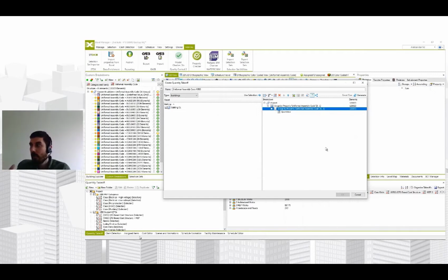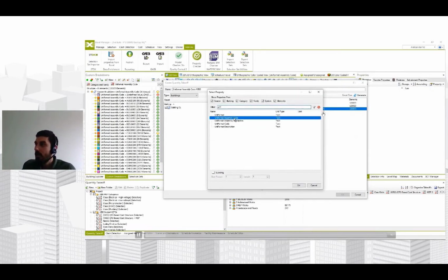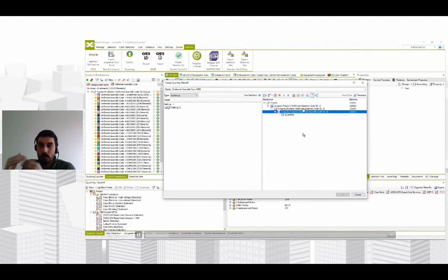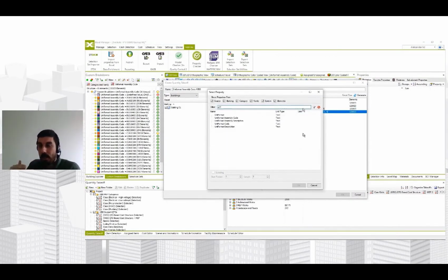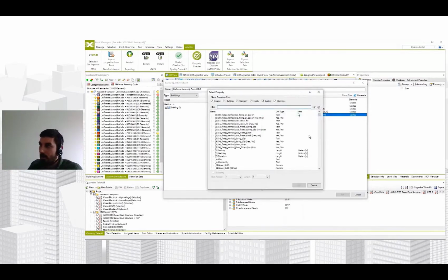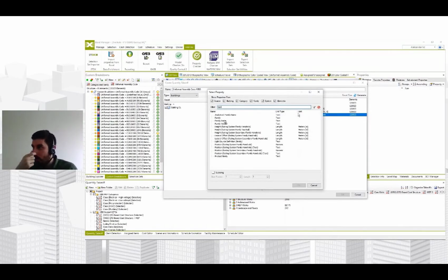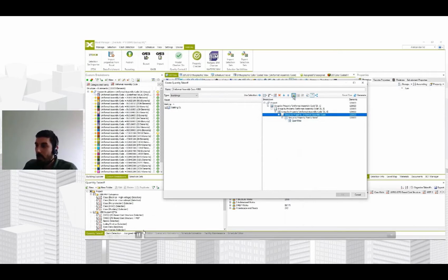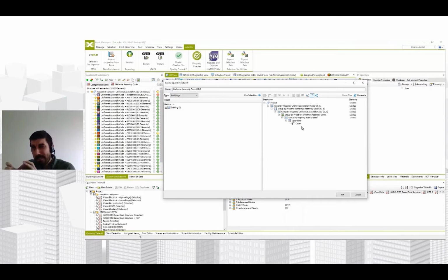Then on the next levels, we're going to use, as you can see, the first three and then the first five letters of this code, so that we can get a pretty nice hierarchy for this cost classification. On the fourth level, we're going to use the complete Uniformat code, of course. And below the Uniformat code, we're going to use the family name. We do this because, within the same group of works, we can later differentiate different subgroups of works.